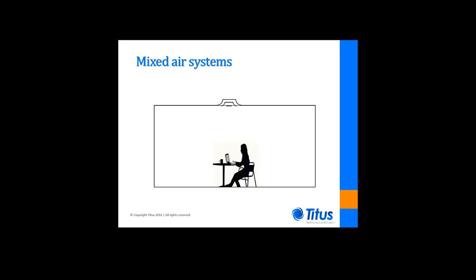Mixed air systems introduce conditioned air at 55 to 57 degrees through diffusers that are commonly ceiling mounted. These diffusers usually discharge the air horizontally across the ceiling, attempting to make use of a capillary effect of the ceiling surface, which is referred to as the Coanda effect. An adequate discharge velocity is maintained to induce room air and mix it with the cold conditioned air such that the velocity and the temperature differentials are dissipated before the supply air stream enters the occupied levels of the space.